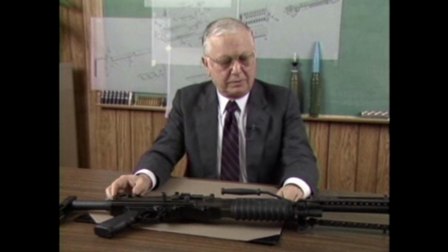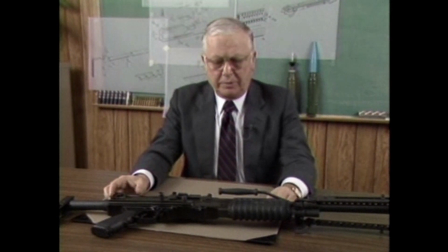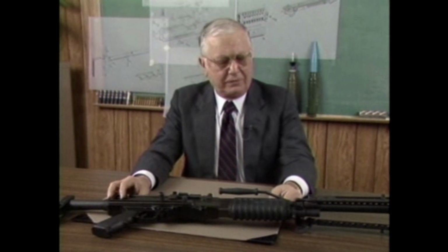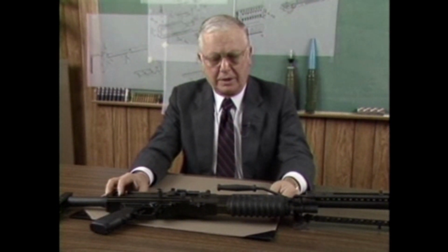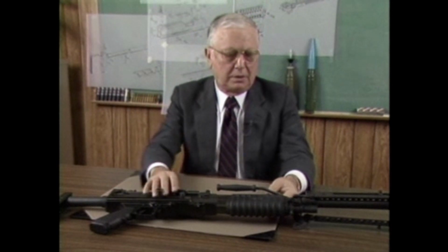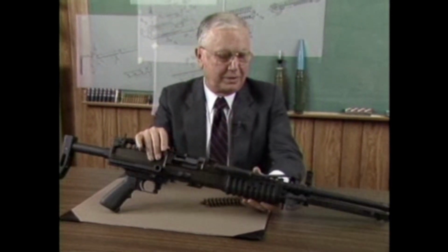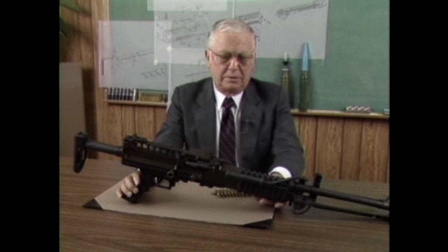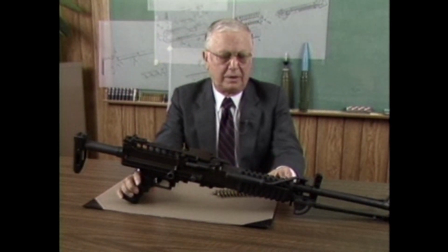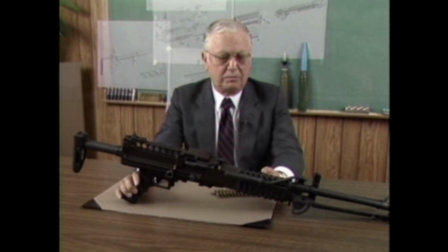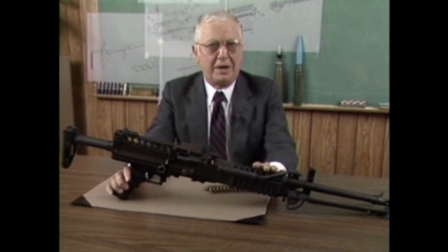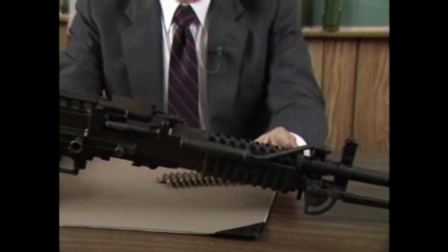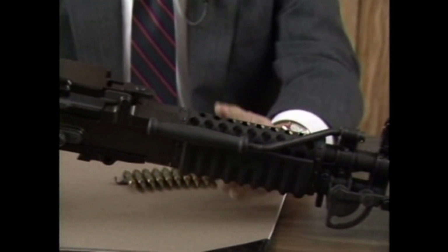Plus, that also means the risk was less. Some of the features that I went down to try to eliminate the deficiencies that were on the 249, and I think if I can rotate this thing around a little bit, I can show you what some of those might be. One of the biggest objections on the 249 was the fact that it didn't have an upper handguard assembly, that the shooters were always burning their hands quite severely because the barrel was exposed. So I, of course, included a handguard arrangement on it.